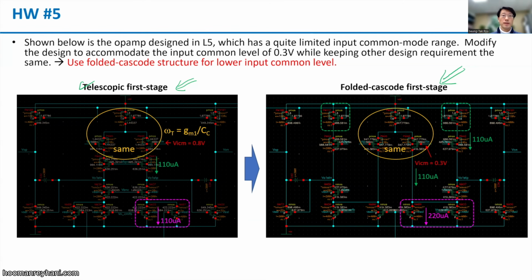And for the output impedance, we have cascode resistance, so we will again have the cascode structure by having the folded cascode, like this. Here we should have a single current source. If you recall, the folded cascode structure will be like this, and we have the cascode here, and the output is going to be like this. This is the first stage, folded cascode.